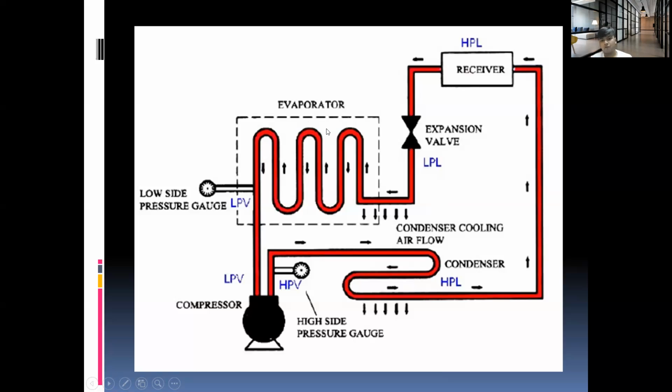What is the evaporator's functionality? Your evaporator changes the phase. The refrigerant from the condenser is in the liquid phase, and from liquid phase it transforms into vapor phase. Once it is transformed into vapor phase, it circulates all around your cooling surface. Then your surroundings, what has to be cooled, get to a particular cooling level. Then this pipe is the recycling point, and it comes again into the compressor.